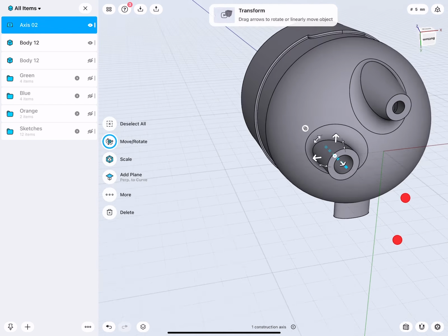This simply makes the transition of this curve to the line smoother. So when I move this one up, there you can see how there's a transition. And you see this is much flatter now. So it's still a tangent transition, but it has more the look of a G2 transition. Okay.